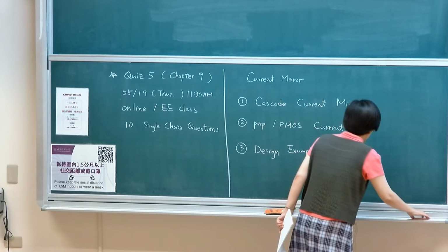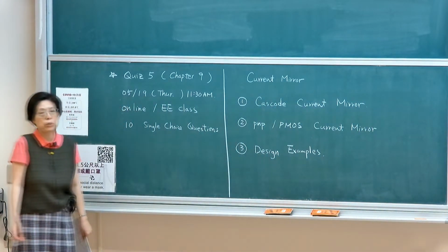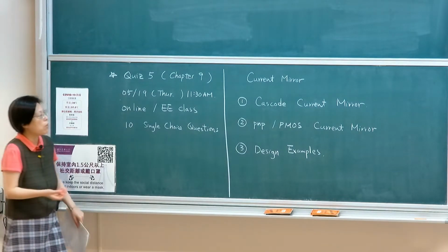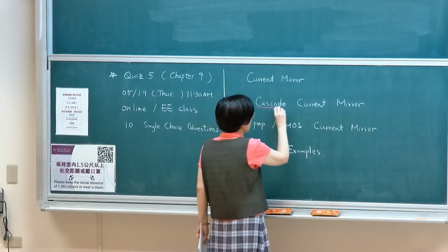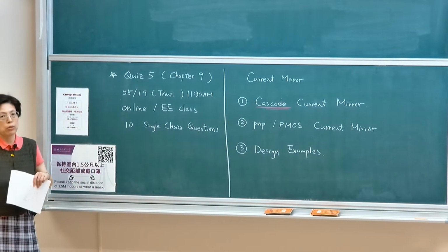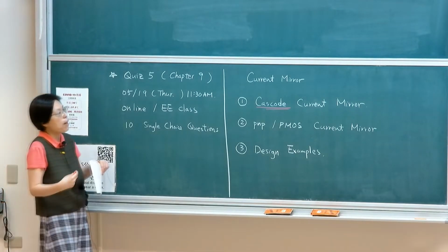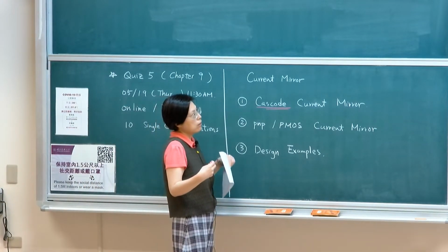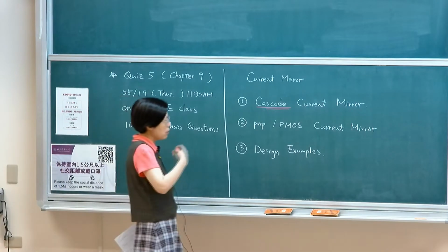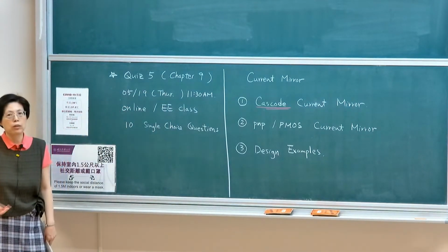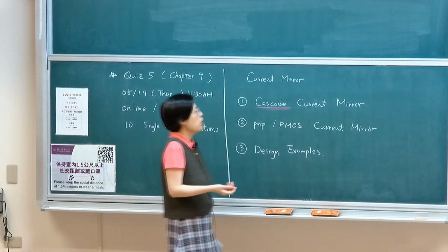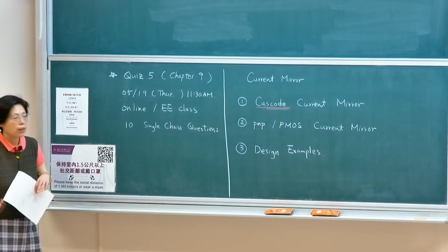Okay? On current mirror, we still have a few topologies or structures to cover. One is the cascode current source or cascode current mirror. In order to provide a cascode current source, you need to construct a cascode current mirror, so we're going to talk about how one achieves that by stacking up cascode structures in current mirrors. Last week, we mainly focused on N-channel or NPN-based current mirrors. We're also going to talk about PNP and how it applies to actual circuits.